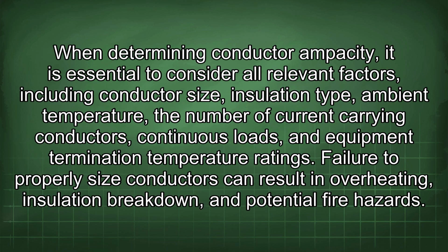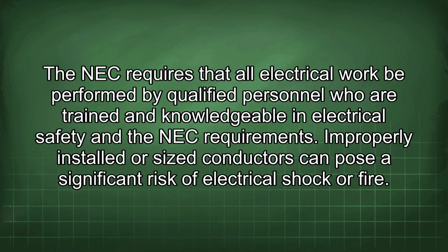When determining conductor ampacity, it is essential to consider all relevant factors, including conductor size, insulation type, ambient temperature, the number of current carrying conductors, continuous loads, and equipment termination temperature ratings. Failure to properly size conductors can result in overheating, insulation breakdown, and potential fire hazards. The NEC requires that all electrical work be performed by qualified personnel who are trained and knowledgeable in electrical safety and the NEC requirements. Improperly installed or sized conductors can pose a significant risk of electrical shock or fire.